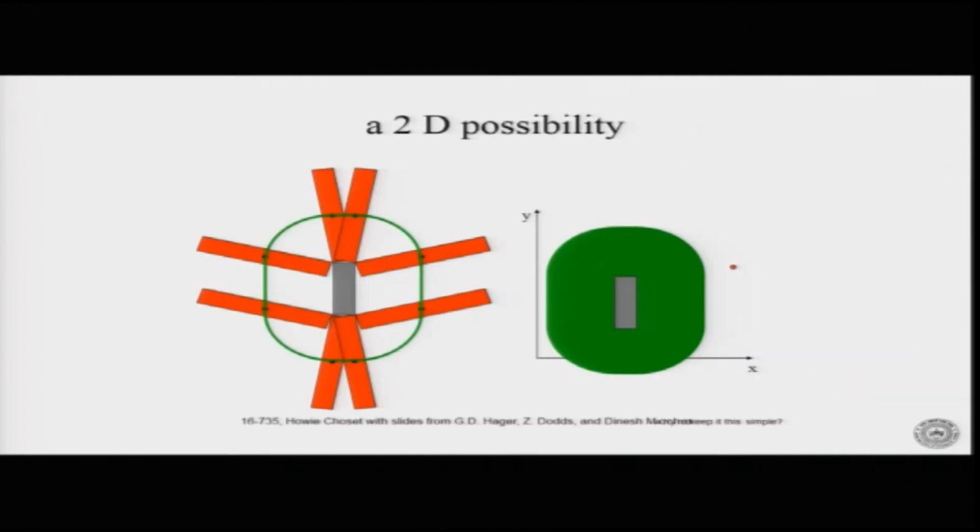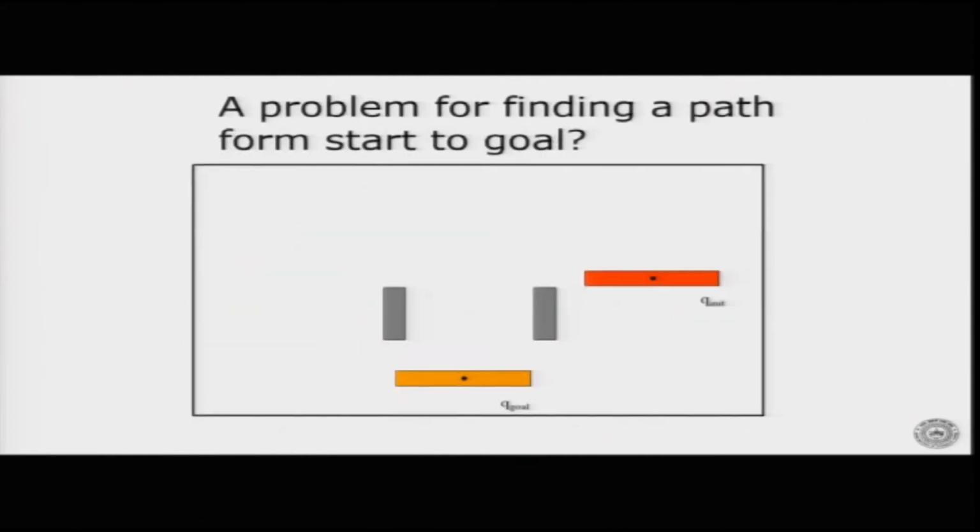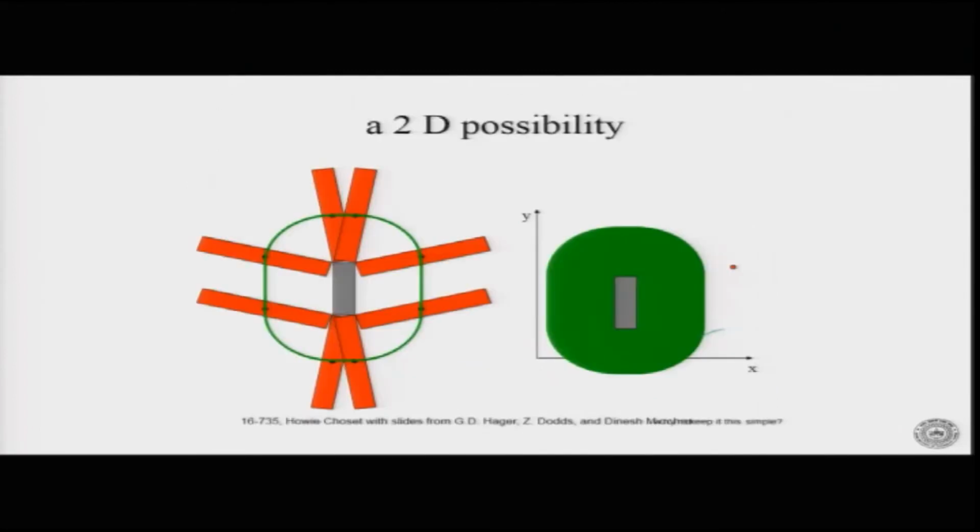Now, if I incline the robot a little bit, then the C space becomes like this. If I keep rotating this robot with different angles, the C space is going to change, and if you combine all of that, then we get the full C obstacle volume. Sorry, not C space. So, this is my C obstacle, not C space.